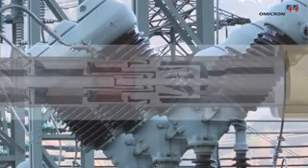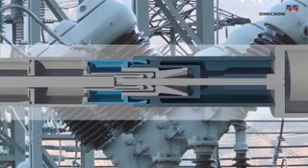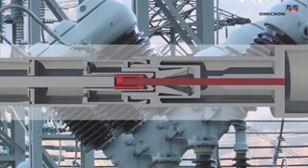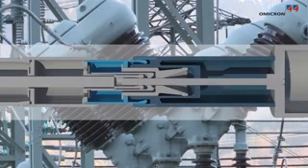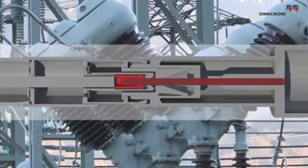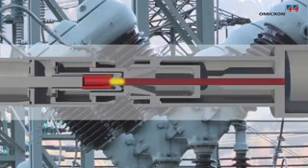Circuit breakers may use multiple contact systems consisting of main contacts and arcing contacts. The main contacts allow operating current to flow with minimal losses, while arcing contacts can break short-circuit currents with minimal arcing erosion.